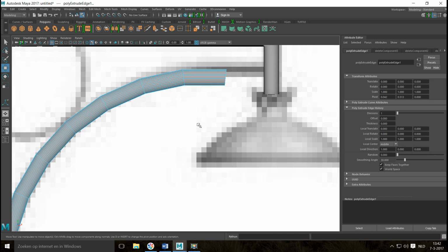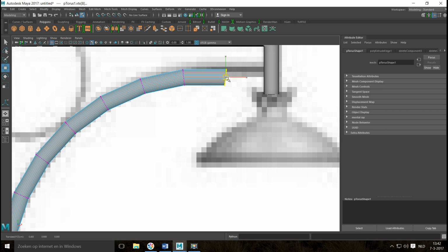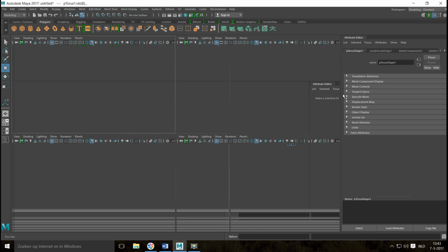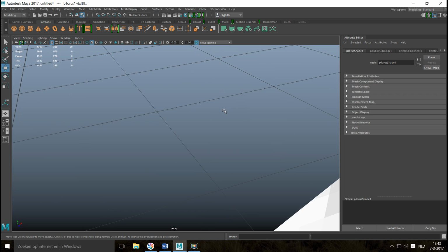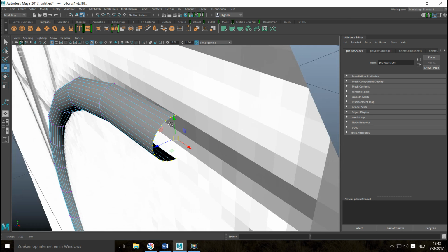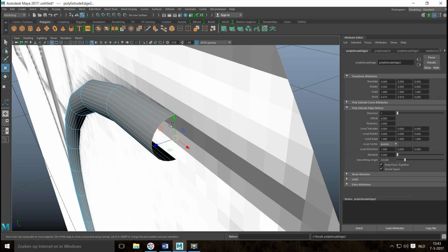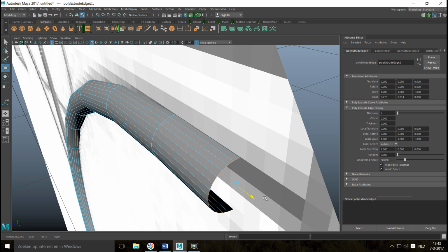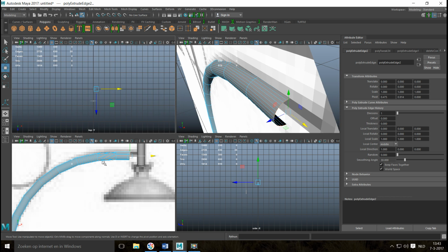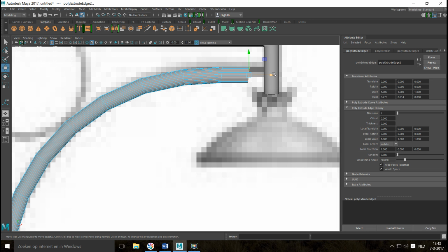And up here, we're going to right click on a vertex, drag select these, bring that up slightly, and then we're going to go in from this view, have to zoom in, right click edge, double click, Control E to extrude, W to pull out, and my reference image is in the way, but we'll fix that in a minute.